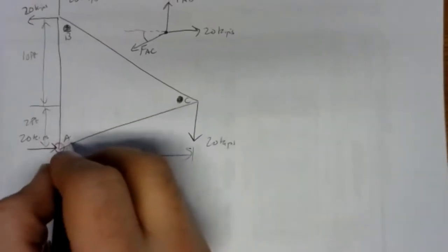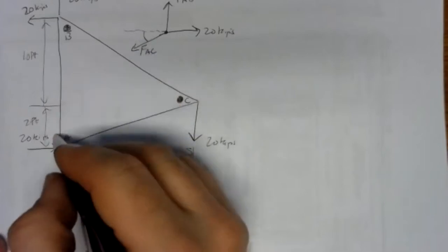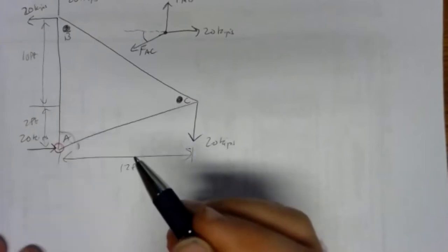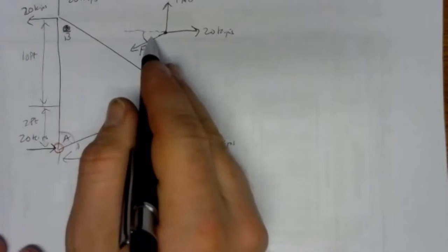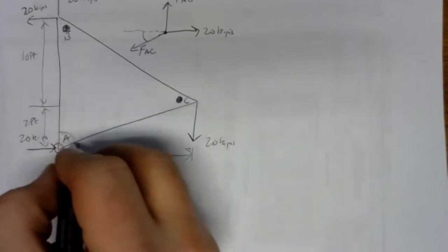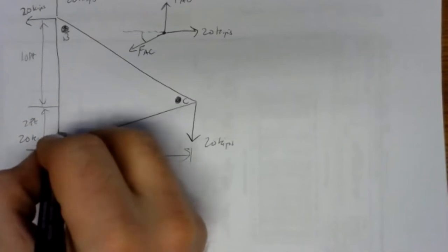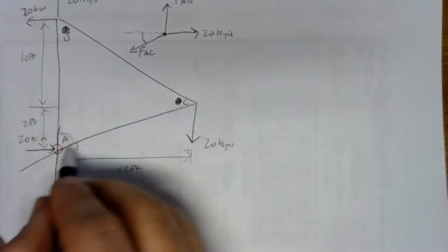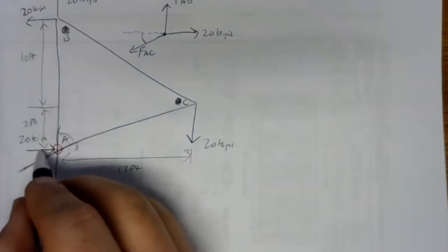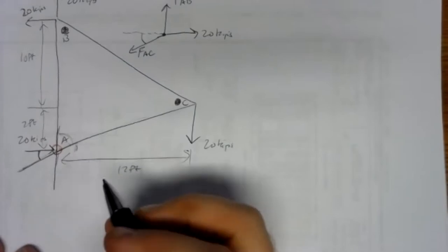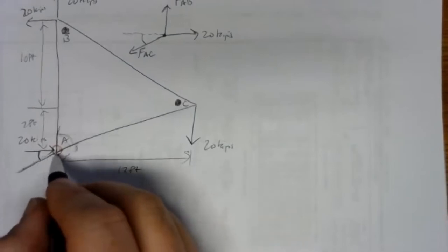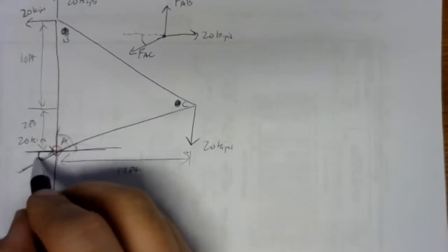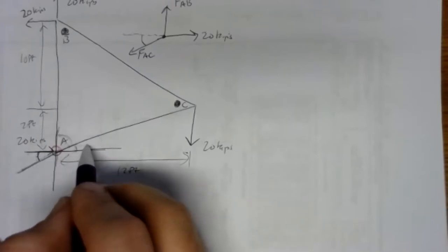It's scrap paper. To be clear, you get the right angle, because at this joint, you could either figure out this angle here, you could figure out this angle here. Either one would work, but which one corresponds up here? It's not always easy to tell. So take the members and extend them out so that you've got a cross there. Now member AC is right here, and I'm looking for that angle right there. When you have a cross going, and you can draw the horizontal in here also, whenever you've got lines crossing, the angles on the opposite sides are the same.